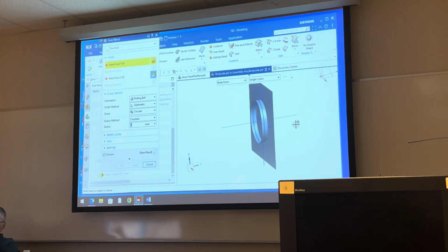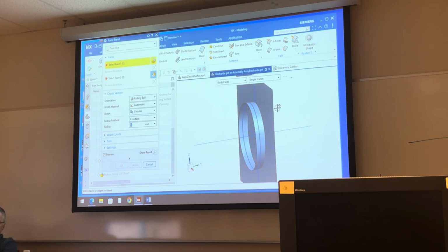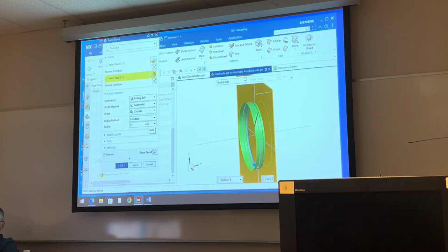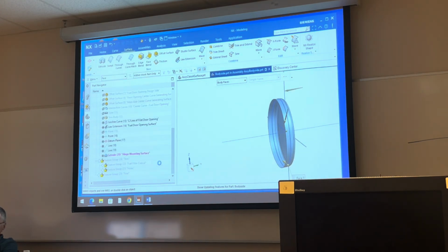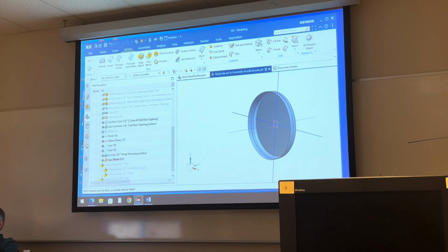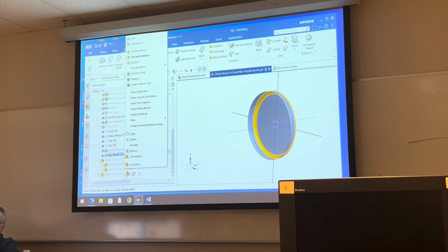Now we're making this radius just more than big enough. Remember, on this type of metal, it should be no smaller than 3 times the material thickness, right? And we're gonna make sure we're way above that. We're gonna say, blend this guy to the back wall at a 6 mil radius, okay? It's gonna go negative Y on that slab, inward on the surface. I'll just hit okay. So there is our fuel filler formed surface, that's the fuel filler itself, before I attach it to the main shape.